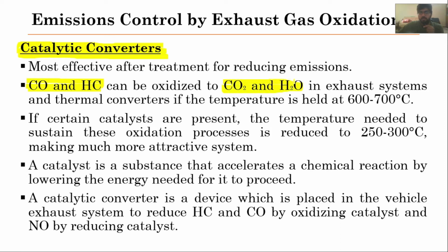Those temperatures were desired in the thermal converters, but in the catalytic converters, since a catalyst is present, the requirement has been reduced to 250 to 300 degrees Celsius. This is the temperature of the exhaust gases we get from the engine exhaust, from the exhaust valve and exhaust manifold of our engine.